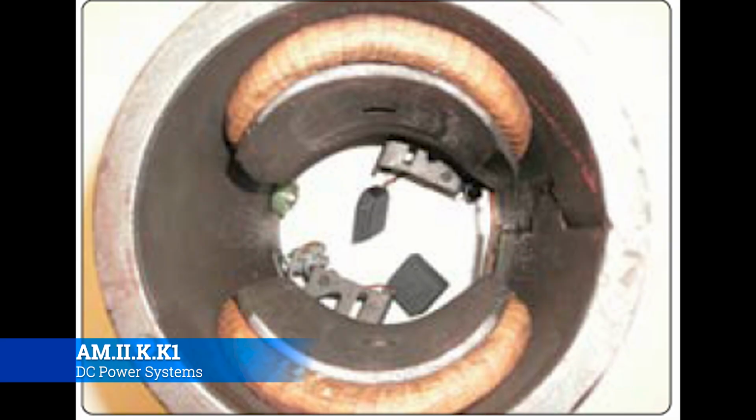All right, this is a picture out of the 8083 of a field frame. It's a much smaller generator than the one that we were looking at, but that gives you an idea. You can see the brushes there on the back, attached to their holders, and then the armature will just slide into this, and the gap between the armature and the field frame is going to be very small. If you think about it like on a lawnmower, the coil gap, which is a very similar type of construction, is a dollar bill that's been folded over twice. It's a little old man knowledge for you.